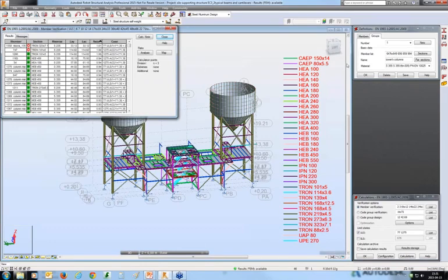So what I'm going to do, as I mentioned, the design cannot be done for a single element. I need to create the groups. I'm going to actually create a new group, and I'm going to type the list of the elements, in my case 2 elements, 1358 and 747, divided by -1, and when I press the Save button, you can see that I actually created 2 groups.